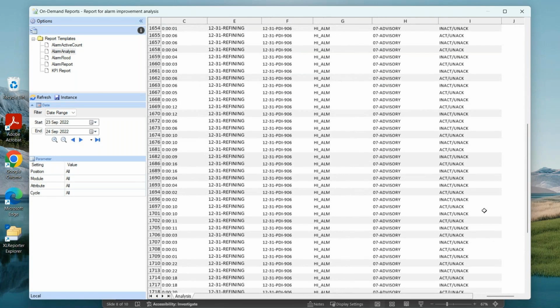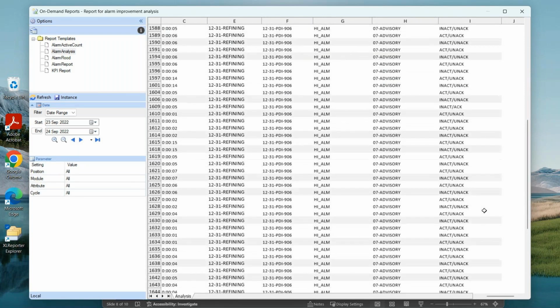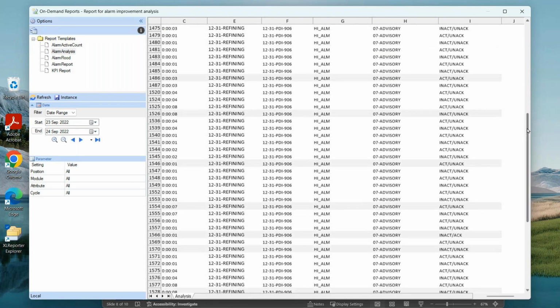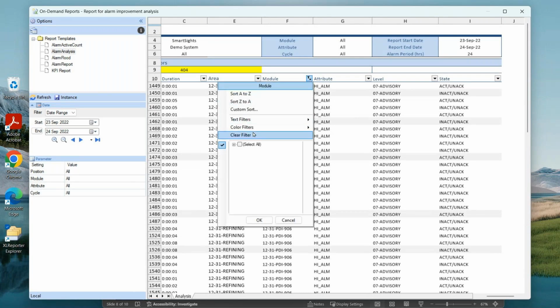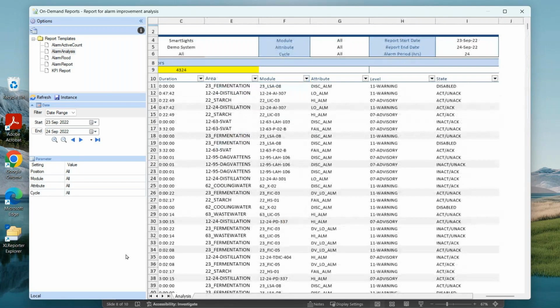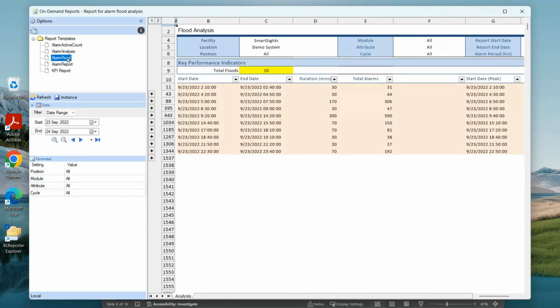So you've got these toggling alarms, cycling alarms here that are taking up resources from the standpoint of attention span for the operator, and something that you probably want to address, all right? Or it's something that you could address. So I'm going to reset the module. Now, when we were talking before, we looked at the alarm flood, and it had a couple of main components there. So let's come to alarm floods, and you'll see here, for example, you've got this one alarm flood here.